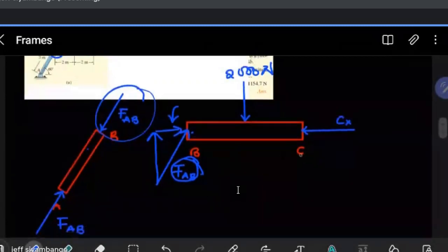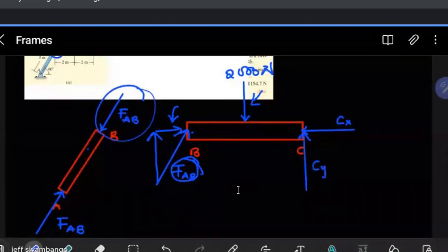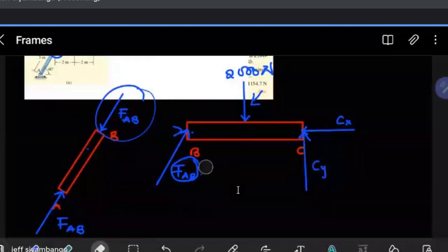And then the vertical component here, obviously it has to balance what this one is doing. This one is pushing down, this one is pushing up. To make sure that everything is in equilibrium, the vertical component here will have to push up. But again, even without trying to reason through, you can just guess their direction and you should still be able to get the correct sense later on. So let me remove these lines I was putting here. And this becomes the free body diagram for our shape. Is that okay?